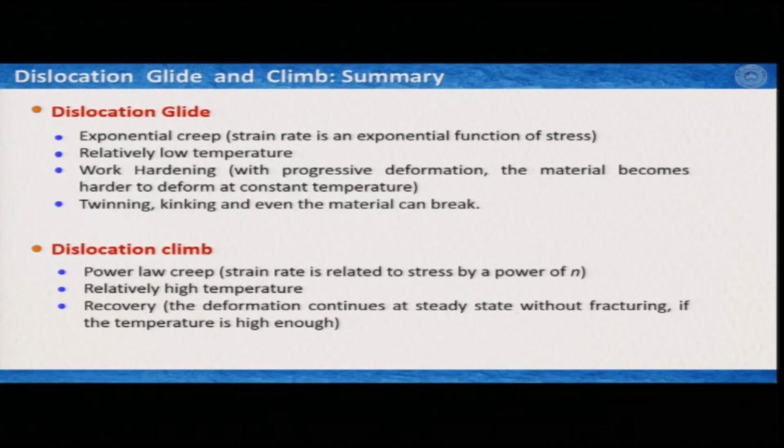On the other hand, dislocation climb is a power law creep. So, strain rate is related to stress by a power of n. It happens at relatively high temperature, and therefore, recovery is one of the fundamental processes in dislocation climb, where the deformation continues at steady state without fracturing if the temperature is high enough.